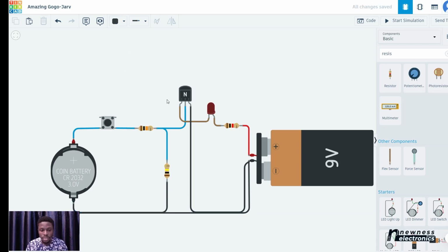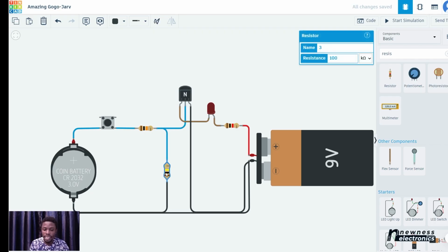Like this. So this is to ensure that the transistor base is always connected. So we connected it via this large resistance, 100 kilo ohms, to ground. This is for the NPN transistor, you have to do this. 10K, 100K to ground, 1K. Let's move this on, 470 ohms, just like we said earlier.